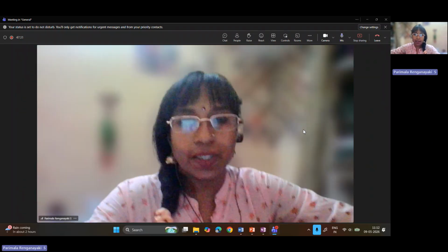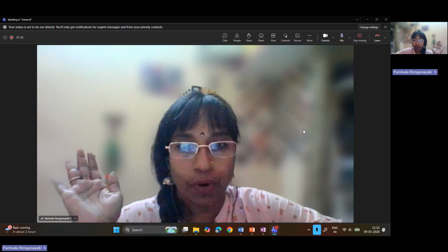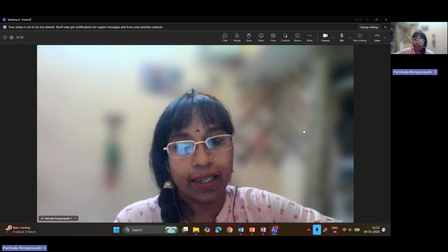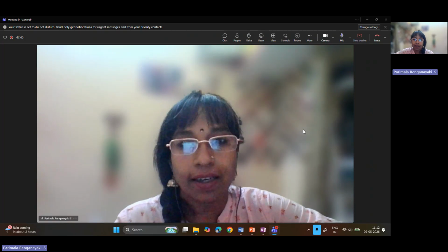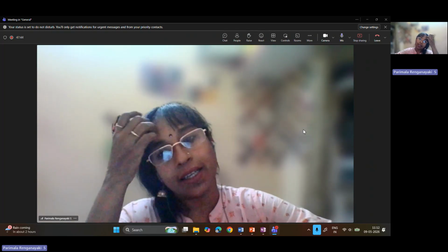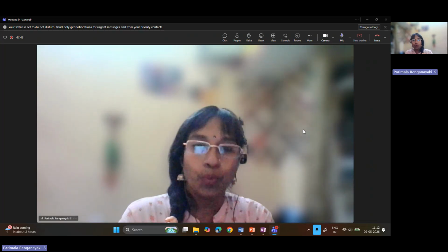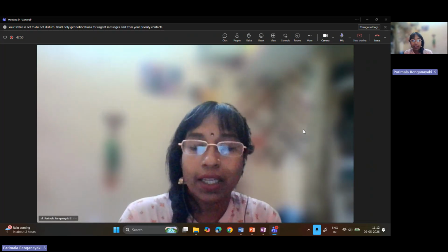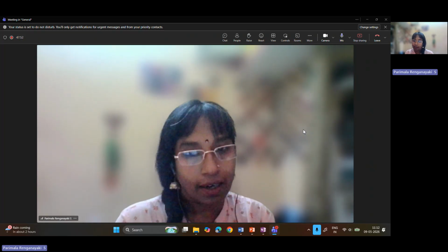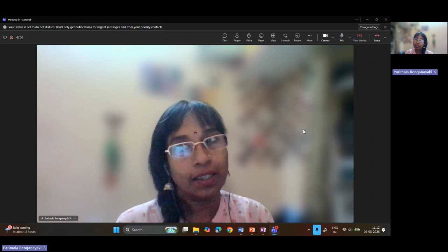So hope we studied the Darcy law and how it affects the movement of groundwater flow with respect to hydraulic conductivity, gradient, area, everything we understood. We have even seen through the cylinder, if water is passing through the pores in reality, how much water can be discharged for the given hydraulic conductivity or I. That was the last problem we solved. Thank you.